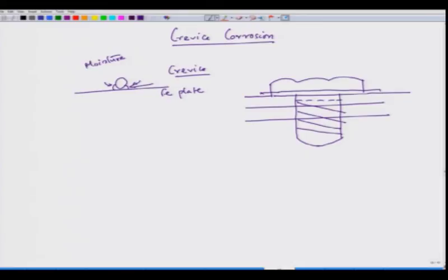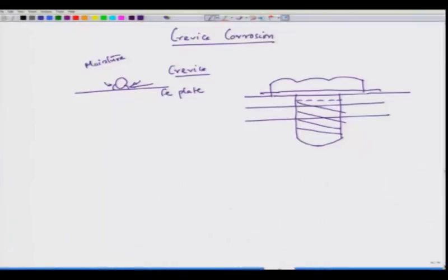What is the reason for this gasket? It will tighten the joint, and it will not allow the bolt to become loose. But if this gasket is a little wide, then the gasket end could have this kind of appearance, and that also forms a crevice. In that section, water can seep in and remain stagnant there. This is another crevice region.